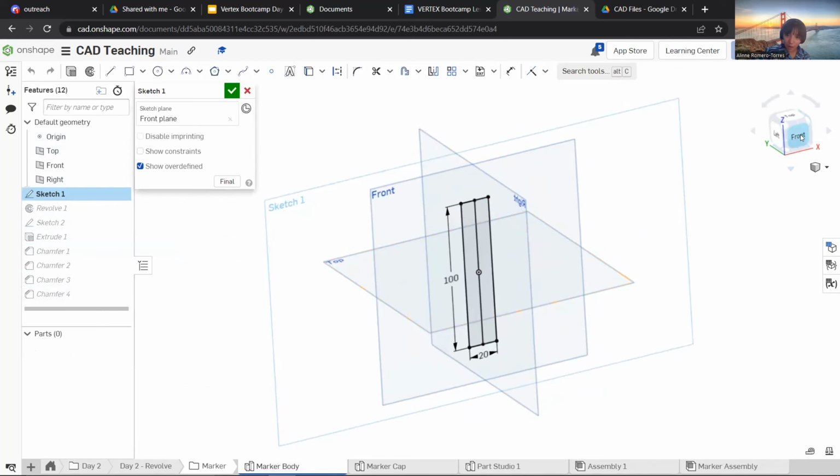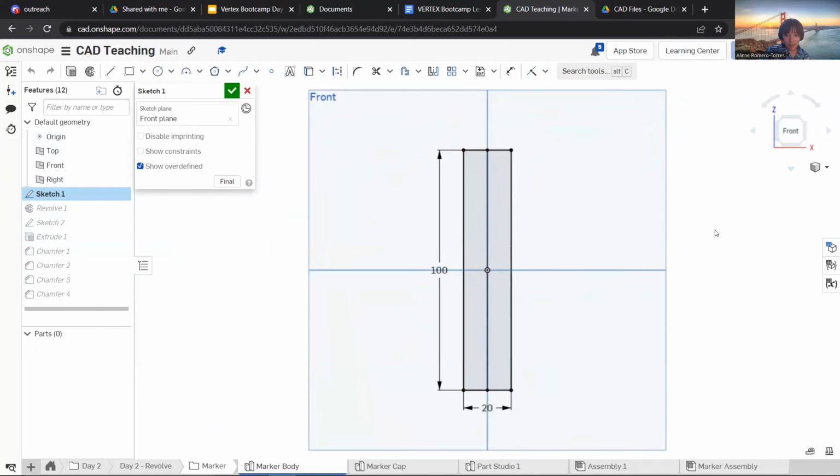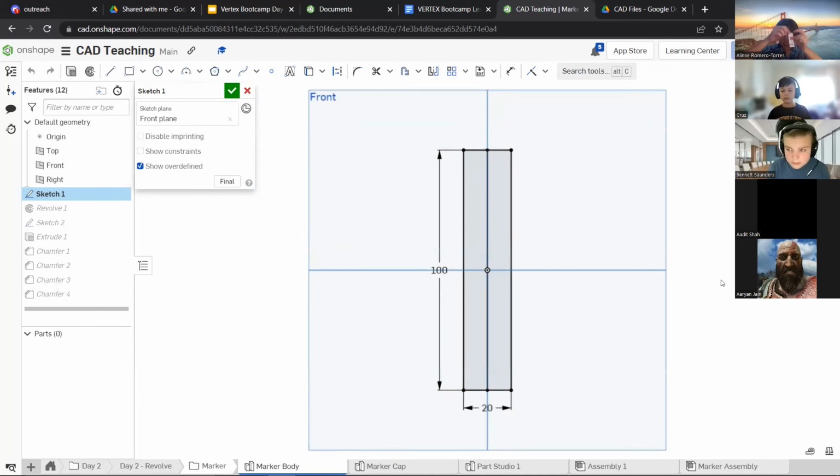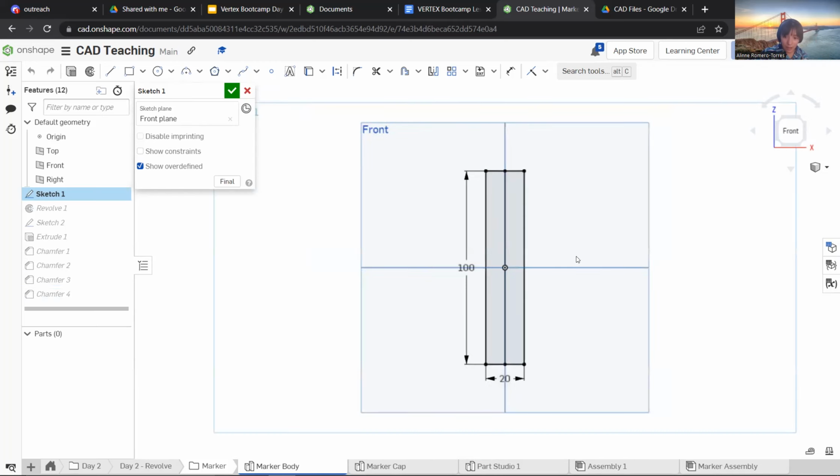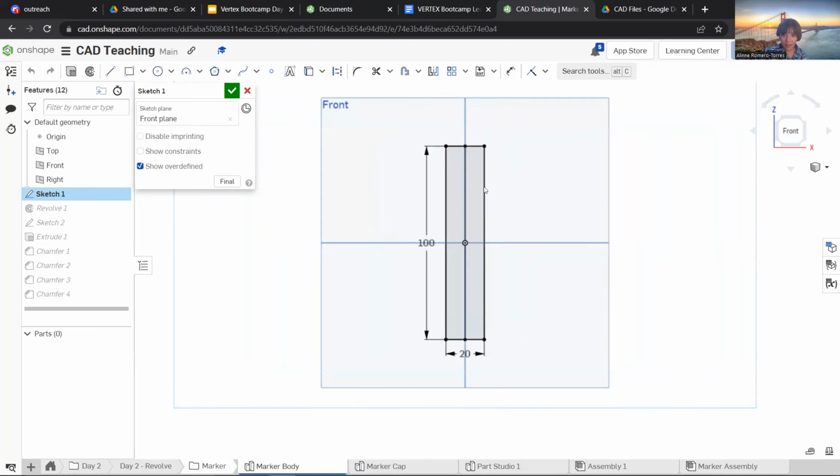So this is using the revolve tool again. If you want to make a cylinder, you have to revolve a rectangle, right? You can imagine this piece of card. It's probably not working very well because of my green screen. But this piece of card, revolving, would make a cylinder. So that's what is happening here. I set the dimensions to make sure it was fully defined. I set a line down the middle because I only want to use half.